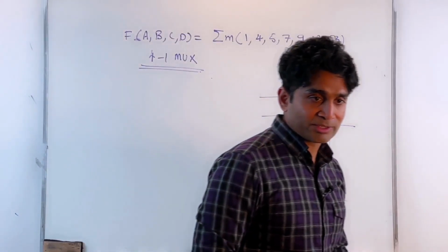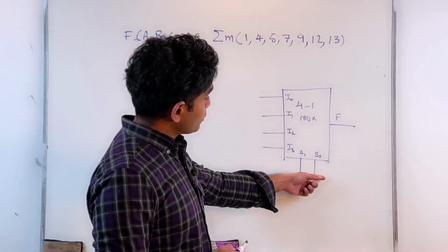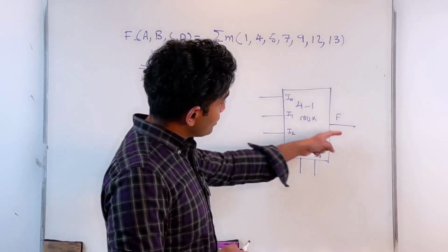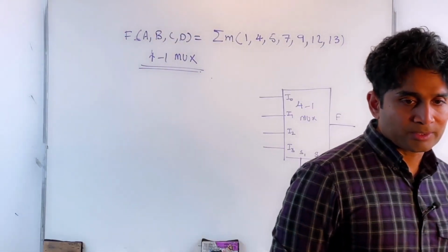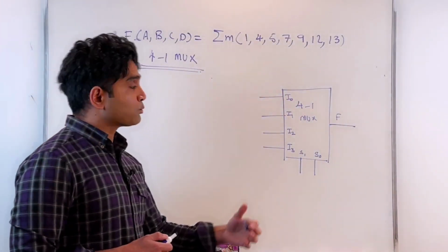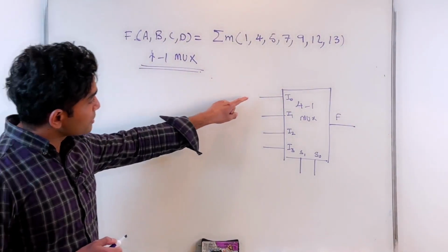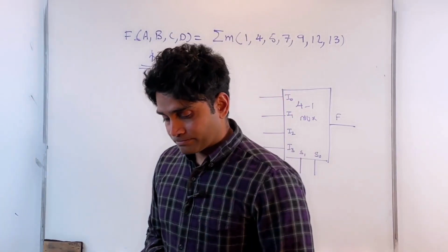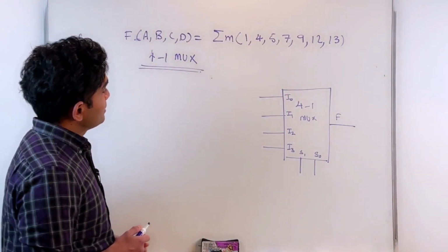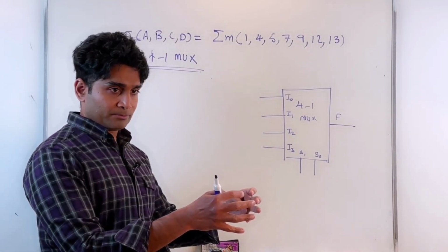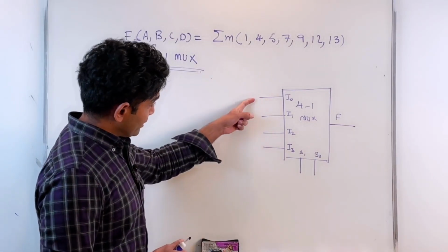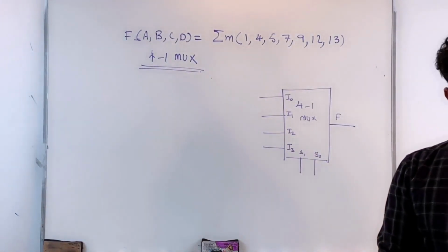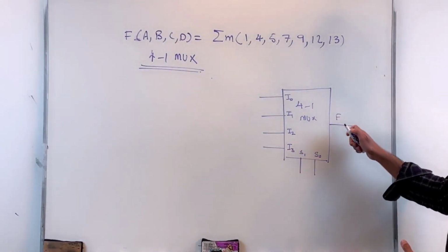Very similar to your telephone exchange. You have 4 calls that are waiting. Depending on whatever you select by applying the right input at the selector inputs, you route that particular call, connect that call to the output. Okay. All right. Now the design approach was, so you have this, right? So these are the terminals. You can classify multiplexers as we have done in the last class into medium scale integrated circuits, right? So I have these inputs. The only things that are available for me as a designer are these inputs. I can only access those inputs. I cannot access the logic gates that are present within the multiplexer. So whatever I have to do, I do with those inputs and the outputs. Of course, my function should be the output here.